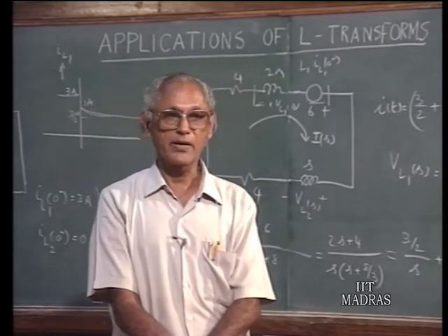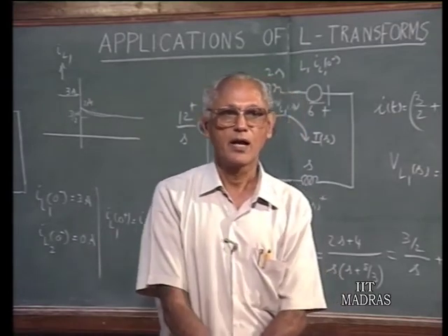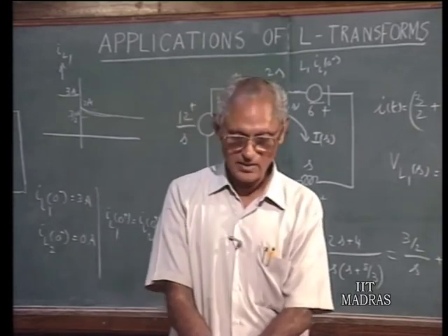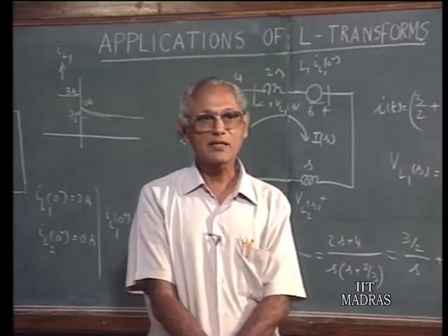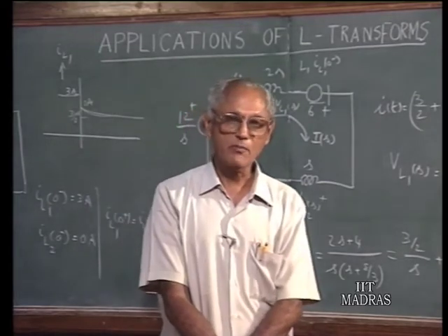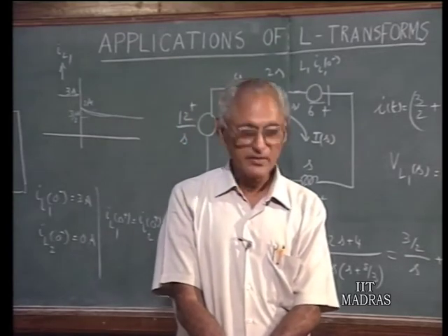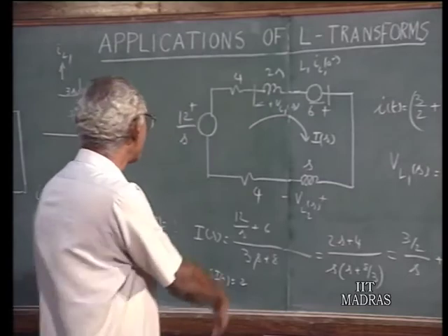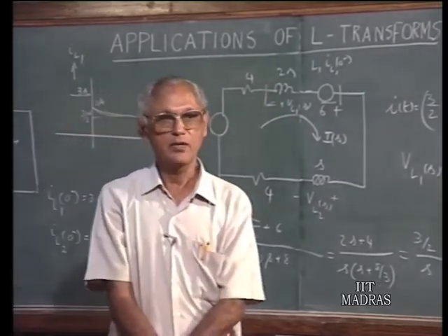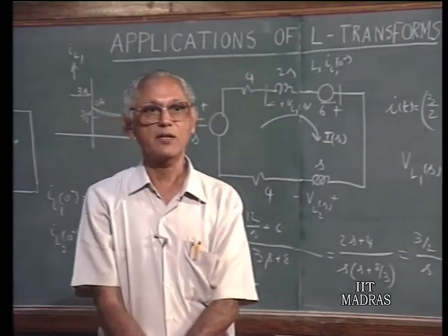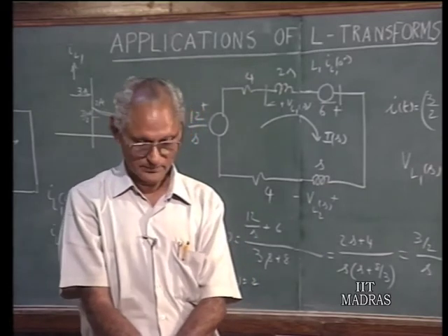And this becomes quite complicated because they are not evident, they are not given with the problem, and you have to calculate this. You have to find out the initial derivative, the second derivative, the third derivative through separate manipulations. All that is unnecessary as far as the Laplace transform technique is concerned. All the initial conditions pertinent to the reactive elements are used in the transform diagram or equivalently in the differential equation. You substitute them and you get the solution. So, separate evaluation of arbitrary constants is not necessary at all in the transform approach.